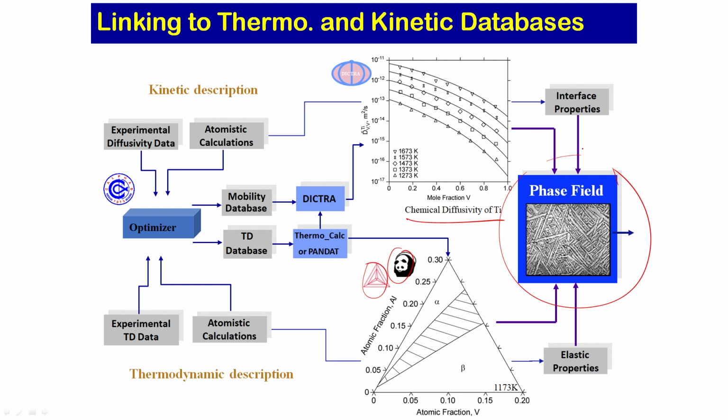As you know, the microstructure will be controlled by many things, not only diffusivities, mobilities, and free energies, but also strain energies. When these kinds of phases are present, you can see in this picture a basket weave microstructure, as we call it in titanium alloys. So, you can have strain energies playing a very important role between the phases.